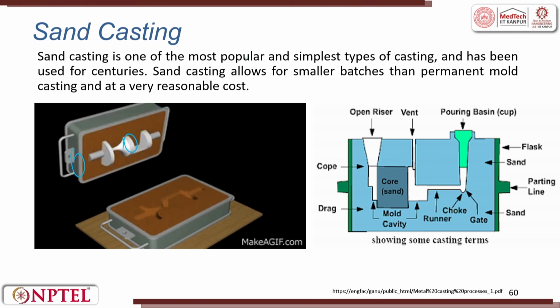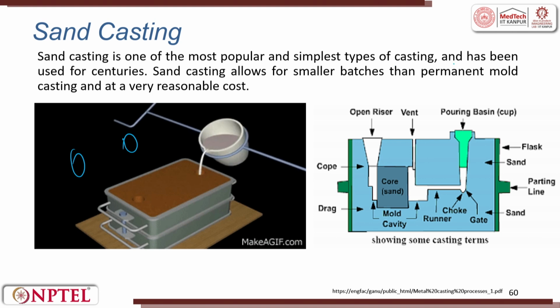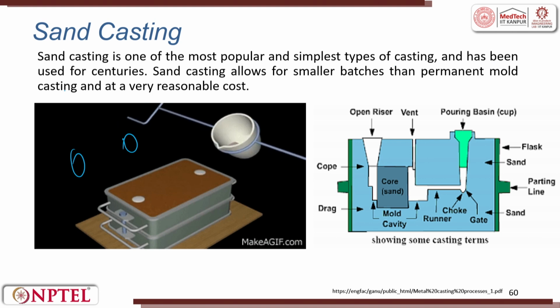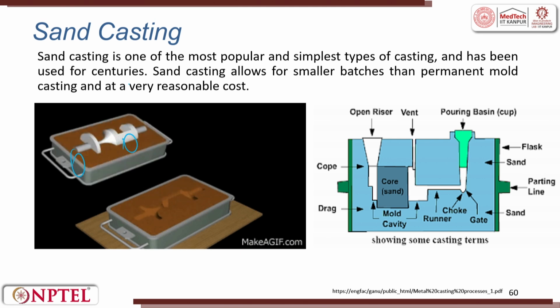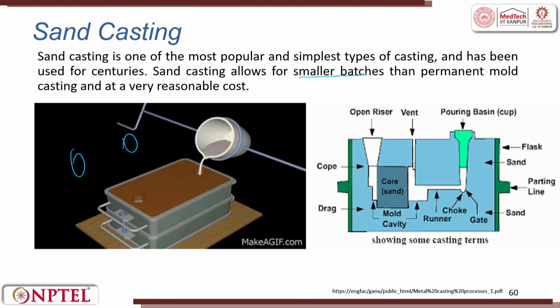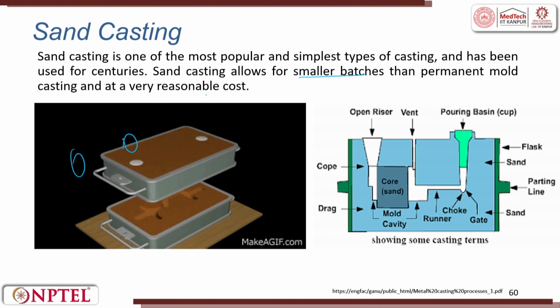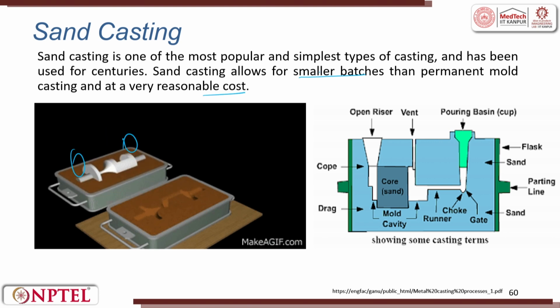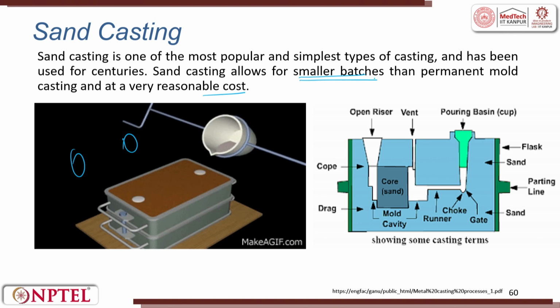Sand casting is the most popular and the simplest type of casting. It has been used for centuries. Even today, if you have a very large component, we always go for sand casting. Sand casting allows for smaller batches than permanent mold casting, and it is very reasonable in cost when the batch size is small, plus when the component is very large.